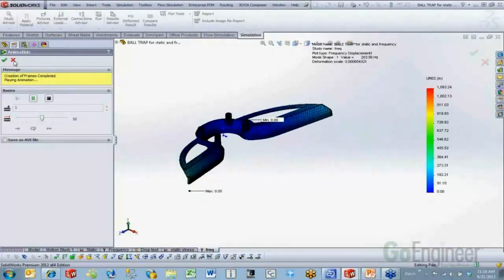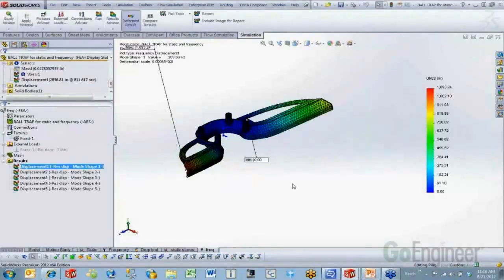Now, if we needed to go a little bit further, and say, if this started to vibrate, what kind of damage is going to occur? With that, we would just move into either a full nonlinear analysis or a linear dynamic analysis, and that would actually allow us to input a harmonic load, and we could get stress and displacement values back.